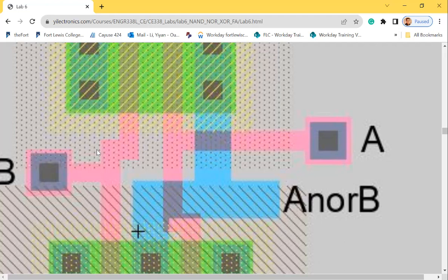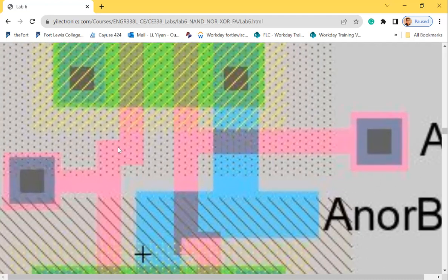There's a resolution issue. So sometimes, in the ideal case, you are seeing a really 90-degree right angle here, but in fabrication, it probably won't be that sharp. It's rounded or something because of the resolution issue. Same to this one. Like the very top of the peak here or the corner here, probably is not just a 1 point. It's probably hundreds of atoms stacking there. So it won't be a sharp corner there.